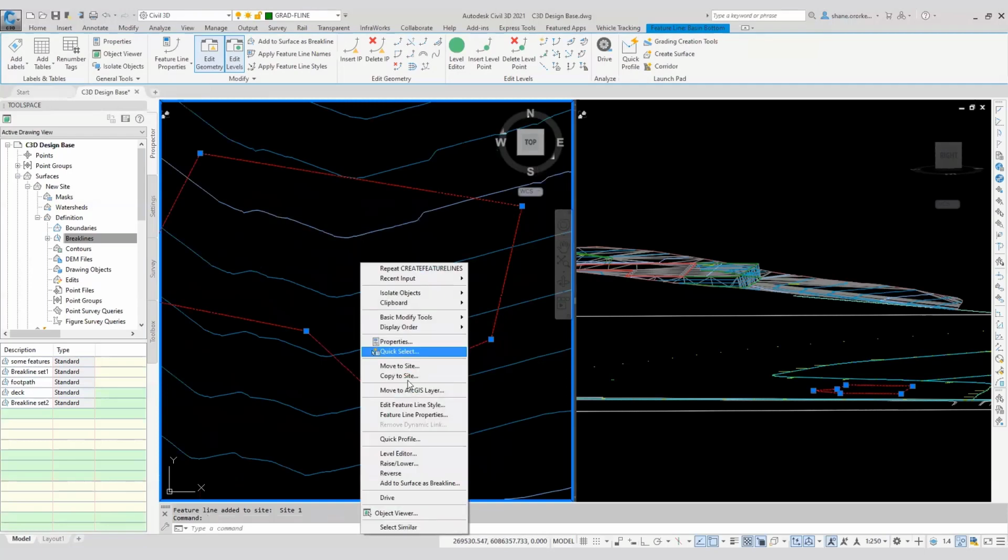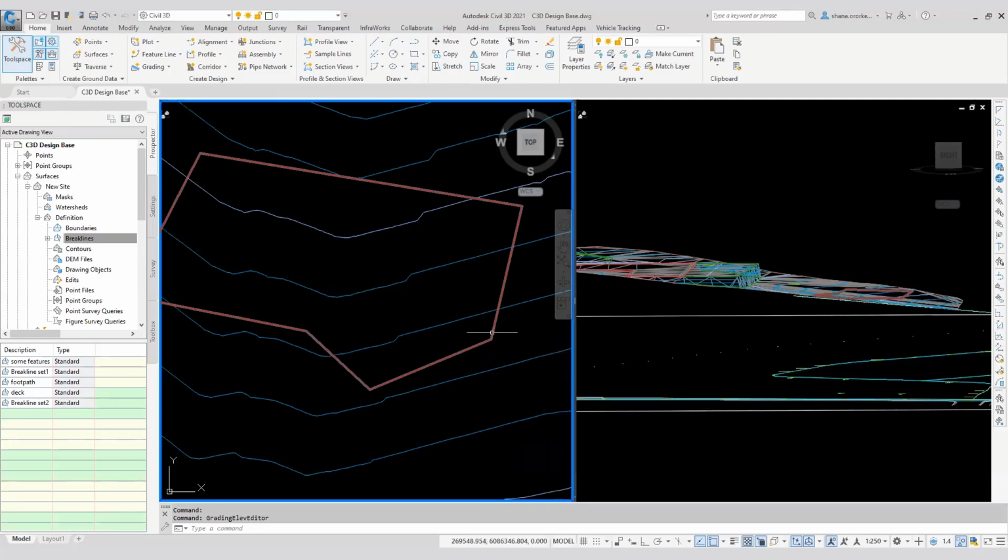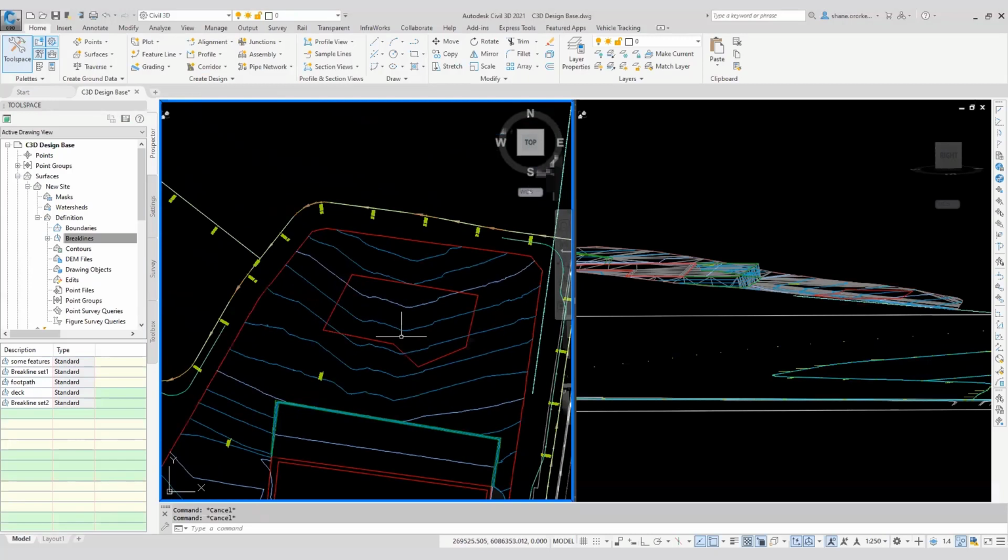Okay, so what I'm going to do is just go into the elevation editor, highlight all these, and I will go with 30. So I can actually see it in 3D here. Could probably be a little bit higher. There we go. All right, so we're going to do a grading off this. Now, I definitely want a flat bottom, but maybe I want something interesting to happen internally. I might show you an example of that in a moment.